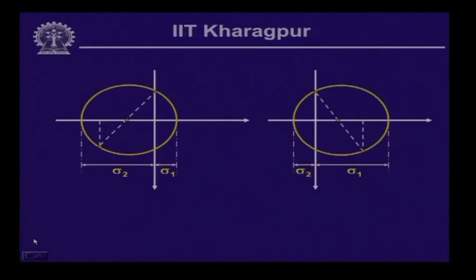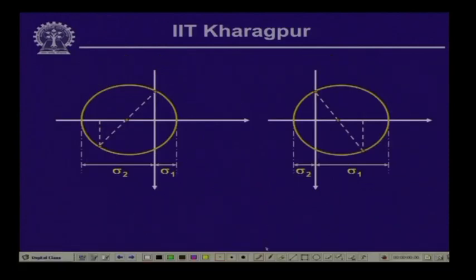Well, this is what is shown over here: if you get the normal and shearing stresses, then you can plot them in the Mohr circle. Here the normal stress is negative and the shearing stress is positive, and that is what you are getting corresponding to the first element. And when your normal stress is positive and the shearing stress also is positive, you get the point over here, and since sigma y is 0, we get the other point over here, and we join them together.